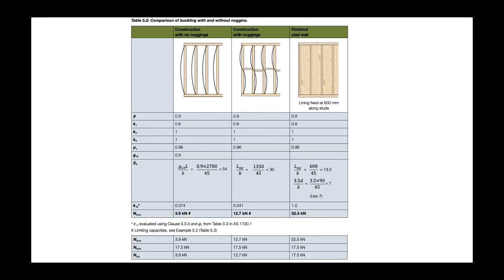The guide takes you through all the considerations and all the factors for use with AS 1720. So stud design is conducted entirely to AS 1720. Design, as far as possible, is done to 1720. And where we've pulled models or references from other standards, we've been quite explicit about that. So all the design assumptions about, for example, effective length, levels of restraint, and so on are calculated through in quite transparent detail.